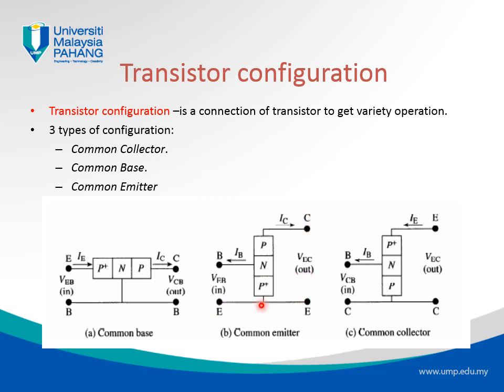And if you remember in the previous slide, if we are in common emitter, then we have a current gain, which we call beta, with the symbol beta. The current gain is therefore the ratio of IC over IB. IB is very small, IC is larger.